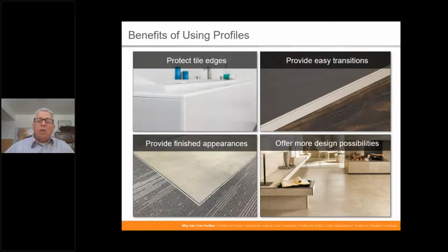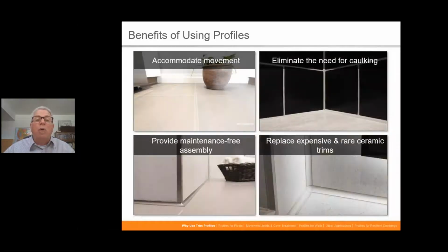So the benefits of those are to protect the edges of the tile, give a nice, clean, professional finish to the edge, do a transition to an adjacent covering, whether it's at the same level or lower or higher. There's different profiles out there for that. And then also just increase the design possibilities. So we're going to look at all of that as we move forward.